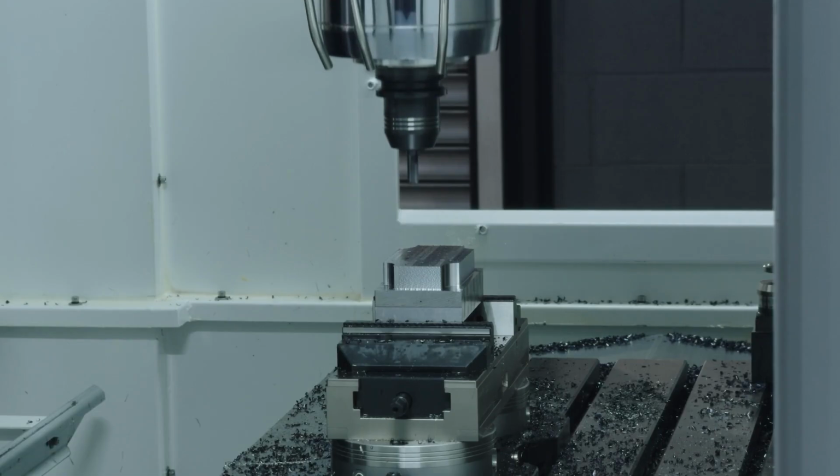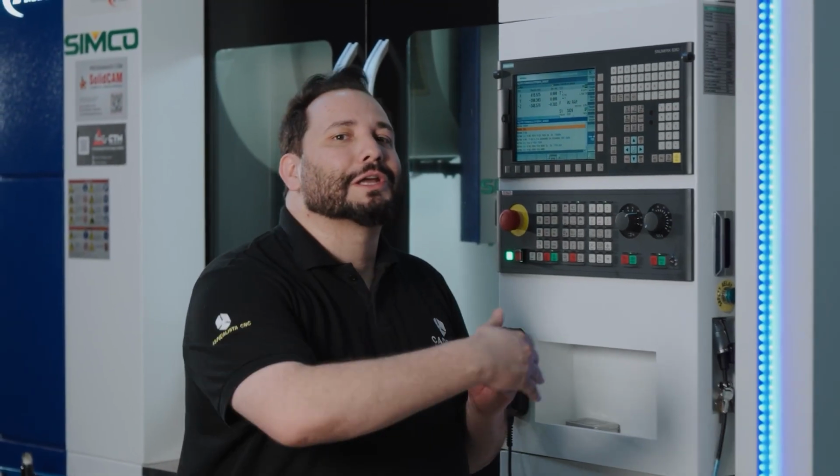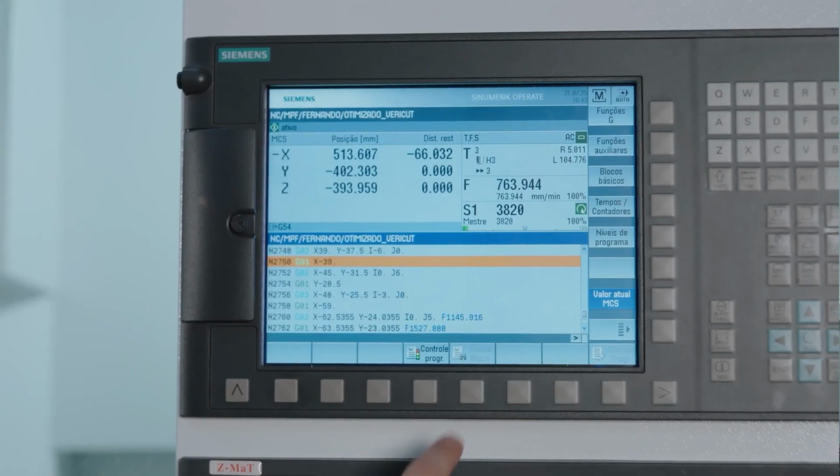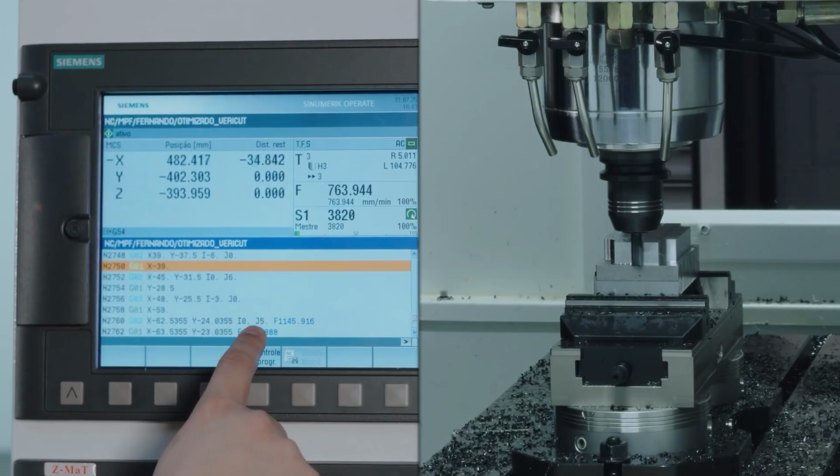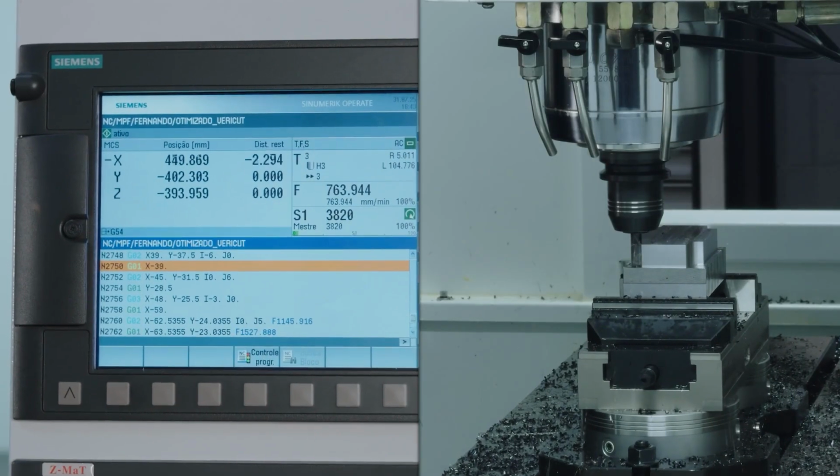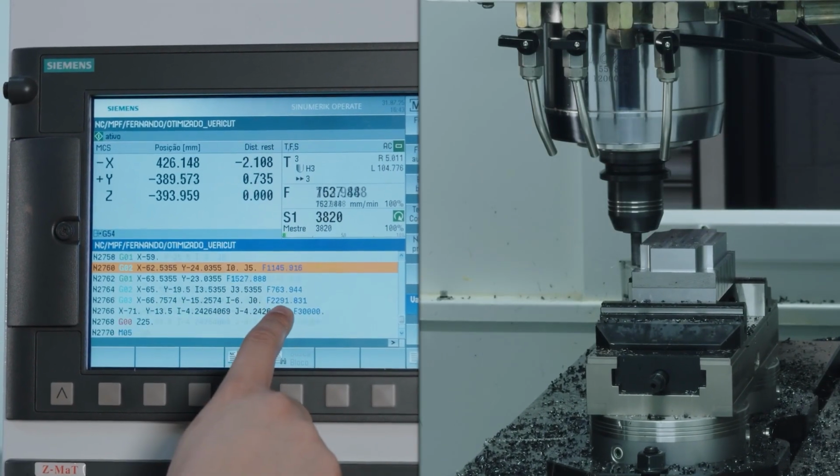Now the 10mm end mill is going to come in. And this is an interesting point. There's a reduction in radius there, and I want to see how the program behaves, how it's going to handle it now. Here it's worth noting the variations in feed rate along the toolpath. And this feed rate decreases when it's in the radius.